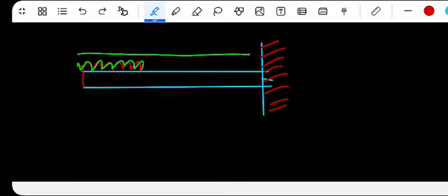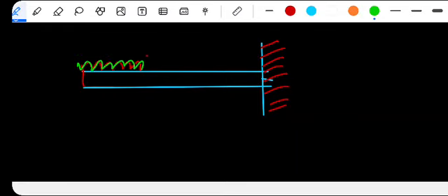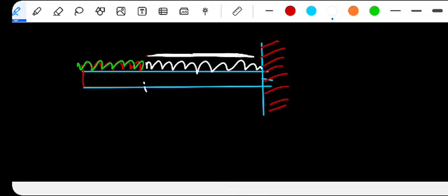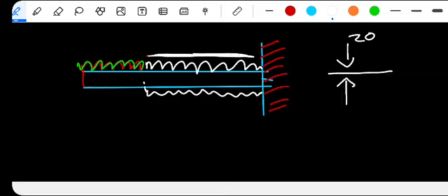So always when you're given something like that, you must make an adjustment. What is the adjustment? You add, I'll use white, your own distributed load. You make it fill up all of this. Since you have added this, you must also adjust what you did. You must take the UDL that you used on the top and also write it on the bottom, to cancel the one on the top. Let's say the force going down is 20 newtons. If I want to cancel this force, I will put another force acting up, which is 20 newtons.